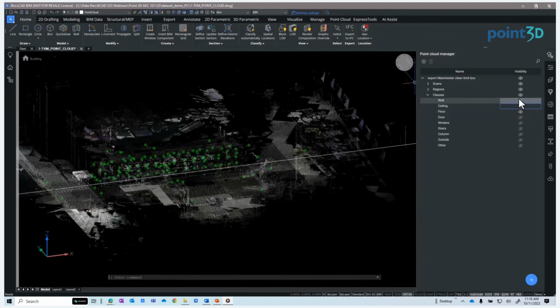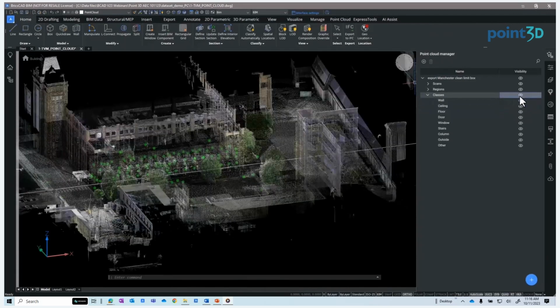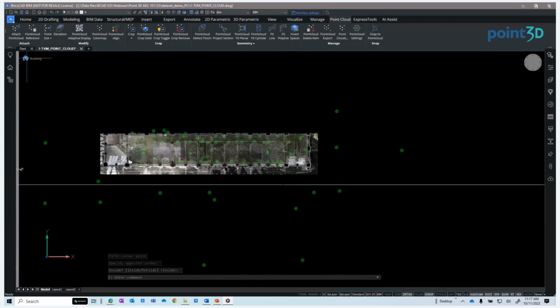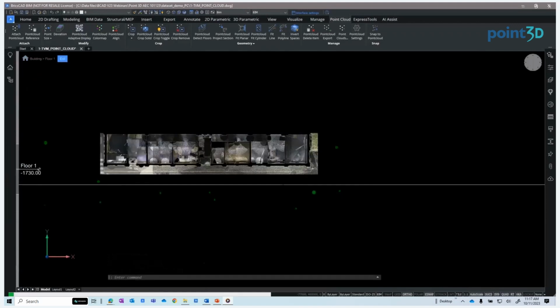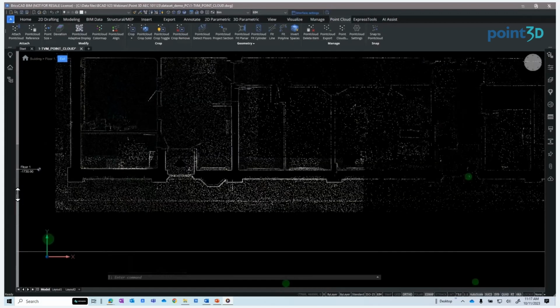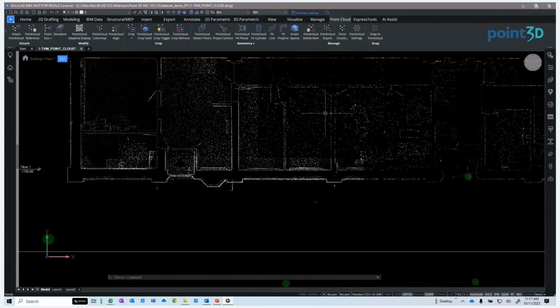All right, so BricsCAD BIM gives you the ultimate flexibility of modeling your designs with direct modeling, as we saw just a little bit of. And now I'm going to show you top view mode. Once the story levels are created in BricsCAD BIM, top view mode can be activated. Notice the floor 1 tag on the left side of the drawing window and the building at the top left. Top view mode is unique to BricsCAD BIM, and it allows you to smoothly switch between working in 2D and 3D views. So you can easily adjust the vertical visibility range to suit your modeling. Think of that as a traditional cut plane when you're drafting.